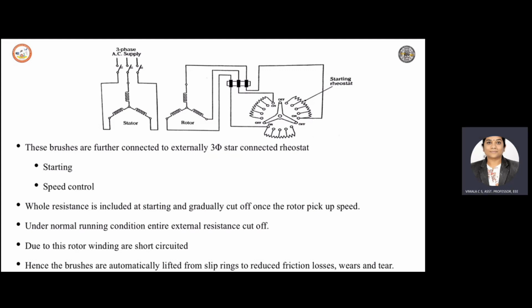So the rotor resistance per phase can be controlled, which affects important characteristics like torque and speed, by adding external resistances. In running condition, the slip rings are shorted. The possibility of adding external resistance in series with the rotor with the help of the slip rings is the main feature of this type of rotor.